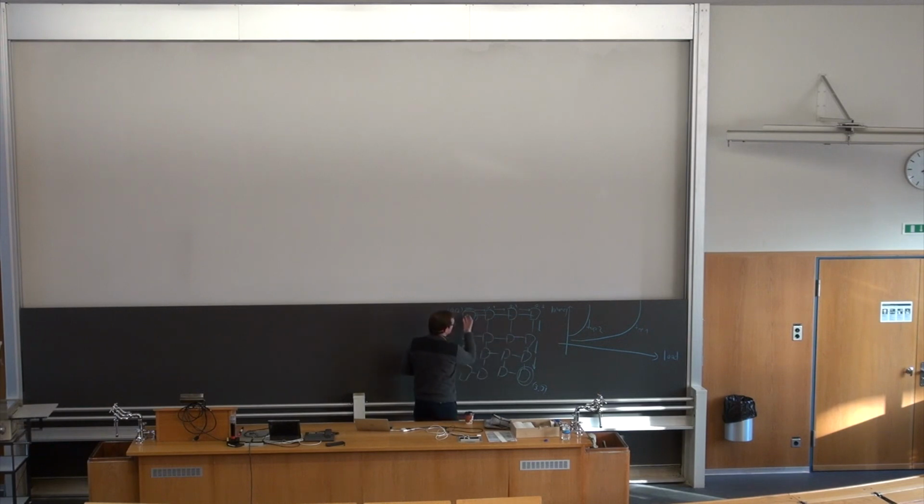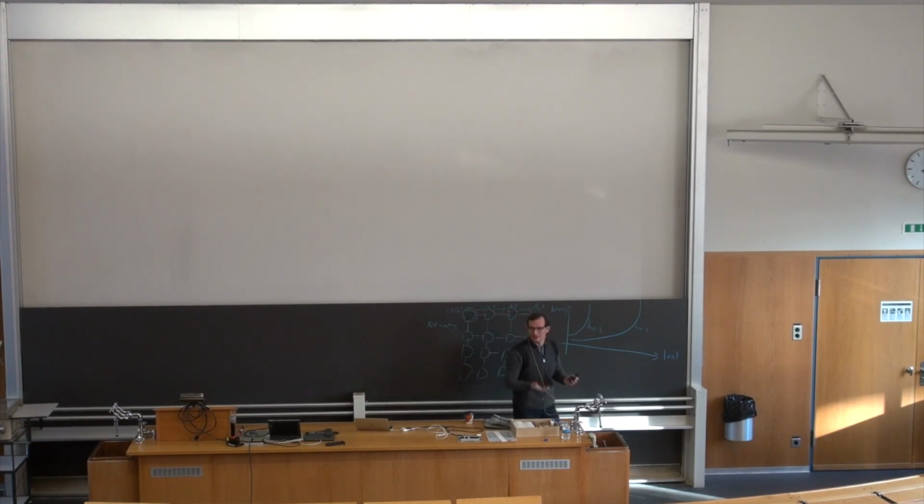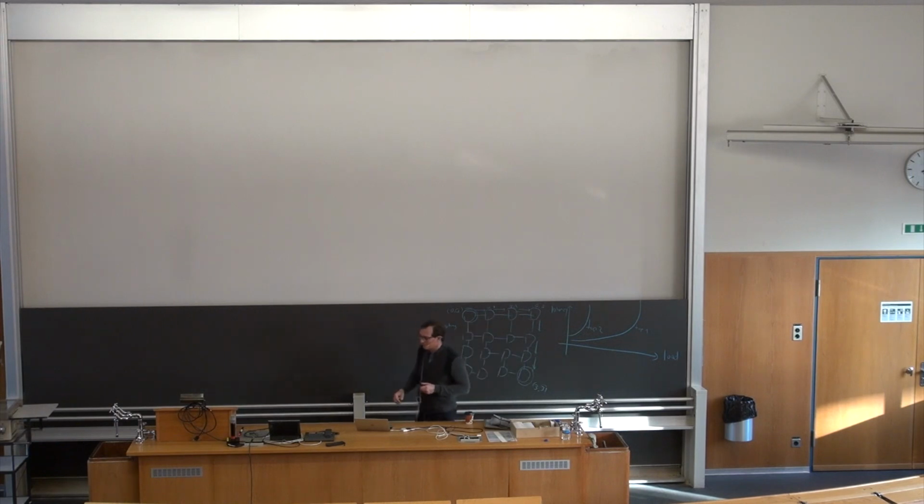But of course, one downside of this sort of routing is you don't exploit the path diversity. If you always use XY routing, this is called XY routing or dimension order routing, you have a lot of path diversity here. You're not exploiting it, you're always going through this route. If everybody is going through that route, you have a lot of congestion in the network, right? So we will see that this routing algorithm is not good for congestion because there's a lot of links over here that are not used if all of the nodes are communicating through XY routing and the communication is happening between these nodes to this destination node, right? So there's a trade-off between simplicity and congestion that you have over here.